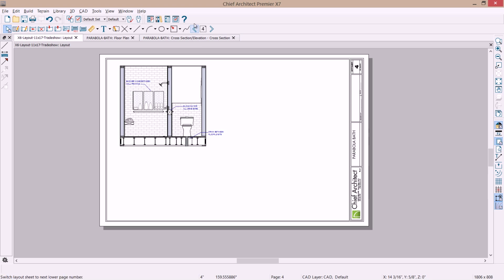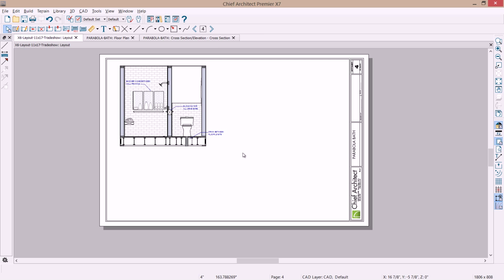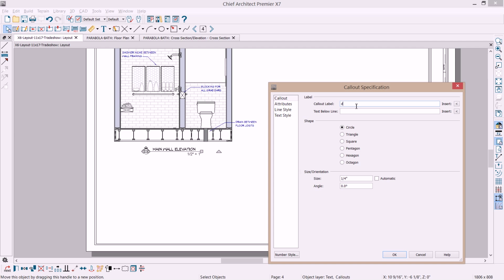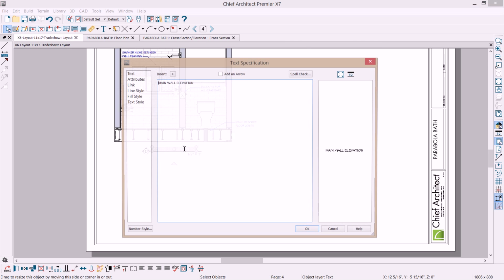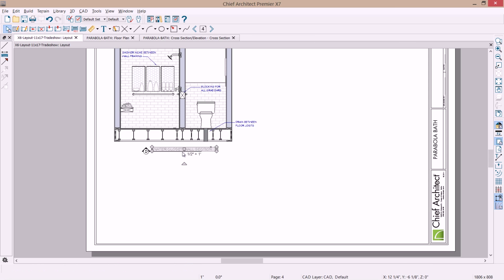And then I'm going to go back to the page that we created that text object, and I'm just going to draw a marquee around that entire item that I want. I'm going to copy that, come back to the plan, and I'm going to paste it underneath here. That was camera D, so I'm just going to modify that with a letter D in there, and then I'll modify the text to the appropriate text. And now I have that information. I may have to stretch that out so that it has the right formatting. And that's pretty much it.